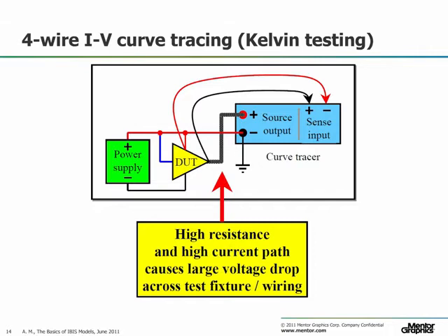This will basically give you the characteristics of your fixturing, and this data can be used for making the corrections on your original data. The correction algorithm is actually not all that complicated. It's just the application of Ohm's law to the two measurements, which can be carried out in a simple spreadsheet type calculation.